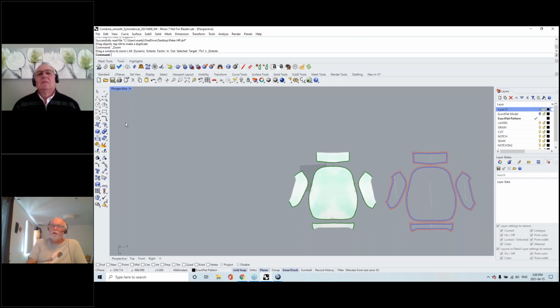And if you're describing a large mining machine, you can certainly drop your mesh resolution just to save memory and file size essentially, but you would have to apply targets along the object as you scan. I'm trying to figure out if the person asking wants to scan parts of a mining machine, which is perfectly feasible, or whether he needs those parts to be connected to each other. If they're going to be in the same patch, then you need to be connected all the way through. And you just simply scan along a set of targets, and targets are just put on randomly. That's the whole point, that they're random. You shouldn't put them in organized lines.